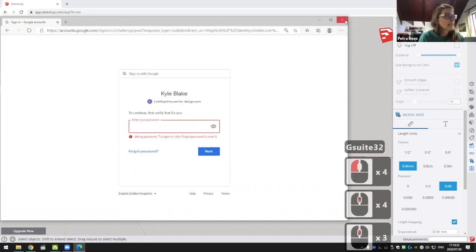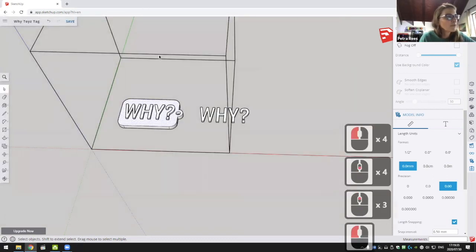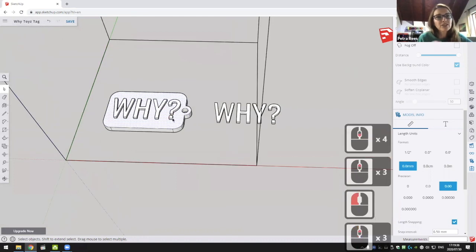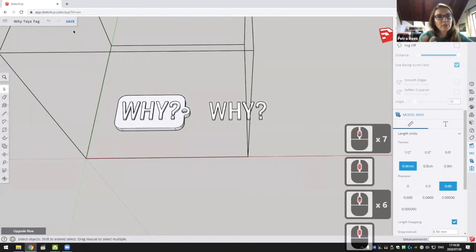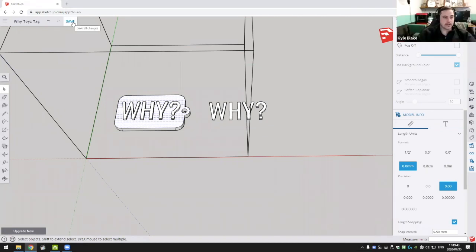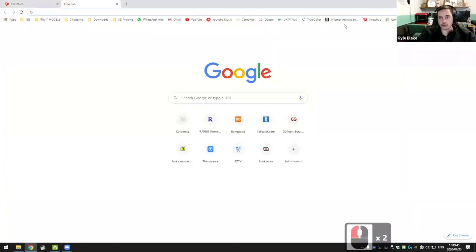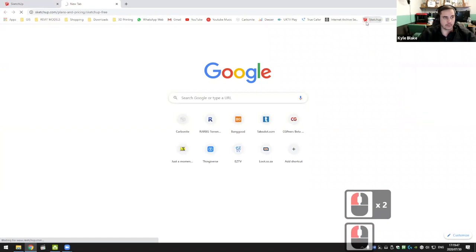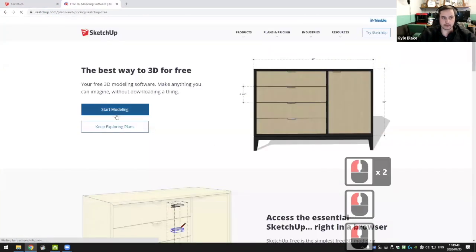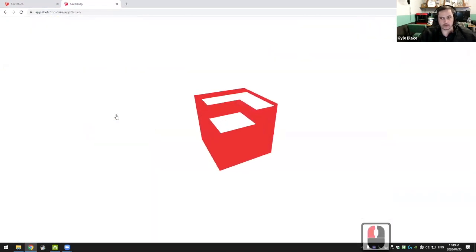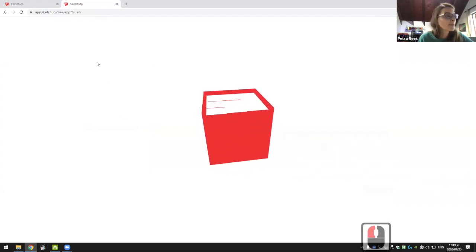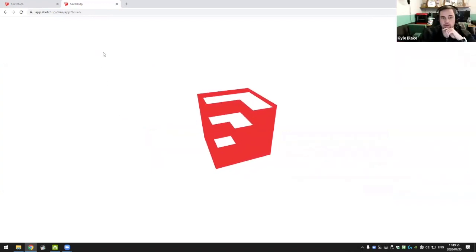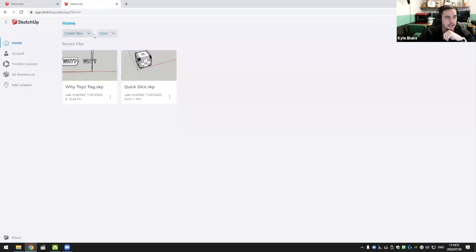Can I permanently set it up for millimeters or inches, or will it always open up in inches and I just need to remember that? No, because you've created your profile, once you've saved something it remembers it. When you click on the top tab to start a new one, so you'll see here, if I say create new, it asks me for simple template in millimeters.